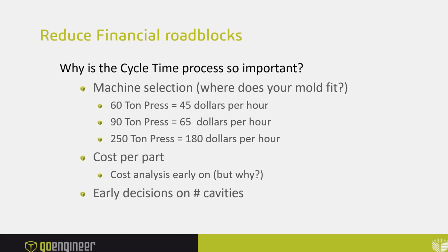So we can calculate this value based off how many cavities you have, your gate and runner and sprue locations and diameters. We can figure this out, right? And what that means for you is that ahead of time you know what type of machine, or rather what ton machine you need to run your mold.